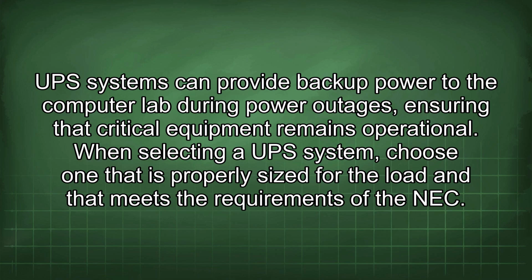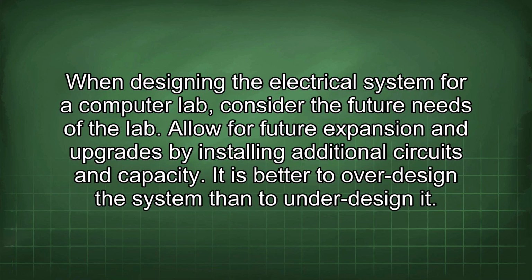When designing the electrical system for a computer lab, consider the future needs of the lab. Allow for future expansion and upgrades by installing additional circuits and capacity. It is better to over-design the system than to under-design it.